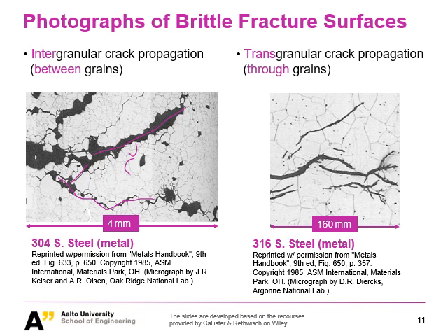As you can imagine, we would have another one, called transgranular brittle fracture. Here, with these dark lines, the brittle fracture is not going along the grain boundary, but through the grains. This is also a stainless steel, called 316.